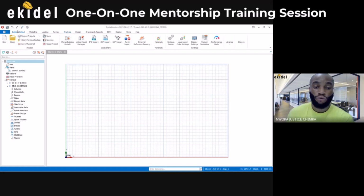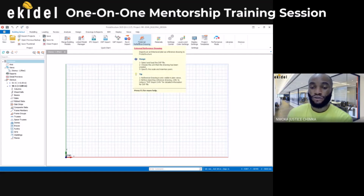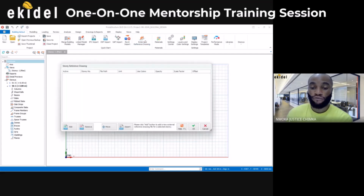So with that, once you've come to this place, the first thing to do is to import the GA drawing that you did. And how do we do that? We do that by coming to this place that says building setout. Under this place, we will see external reference drawing. I'll click on external reference drawing here and wait for a while.